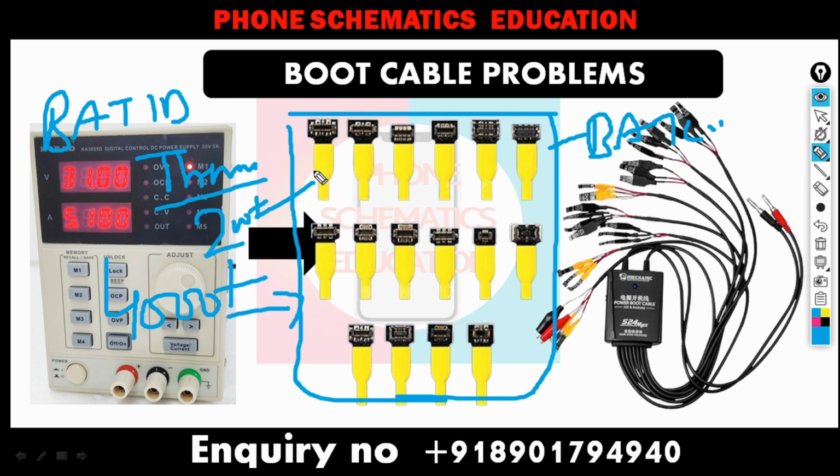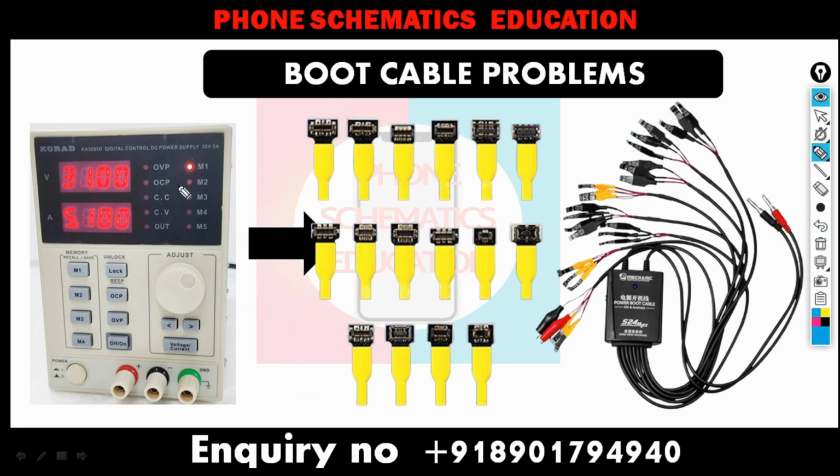Suppose through this connector you try to boot up a phone from a different company. It won't boot every phone, because every phone has a different circuit. For example, take any company with different models: in the ID line or thermal line, if one model uses, let's say, a 50K resistance, another uses 100K.